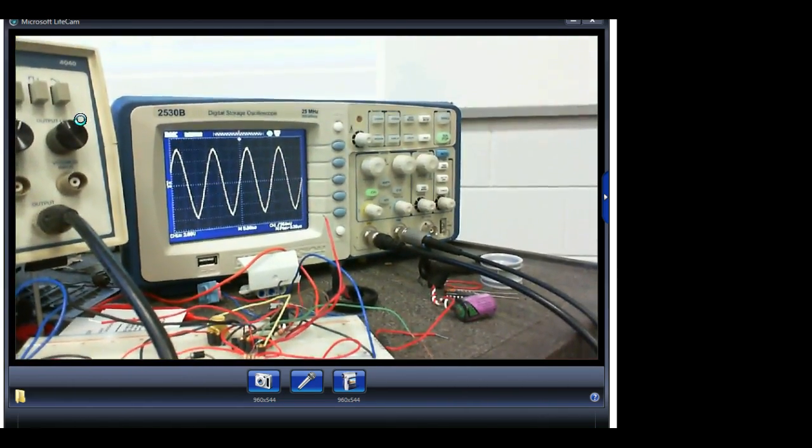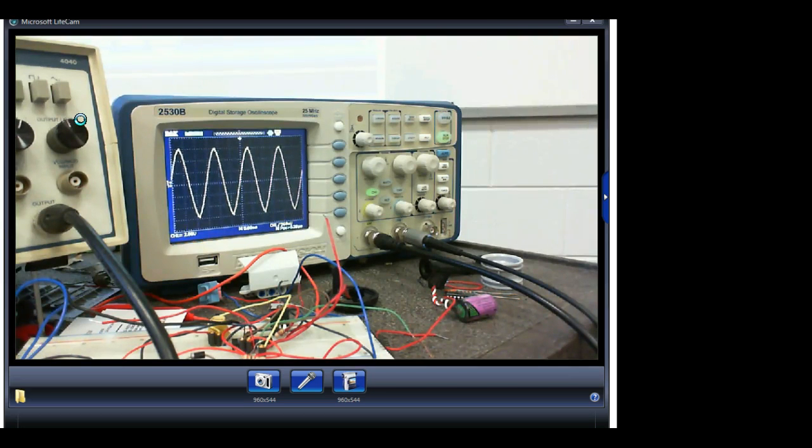So what should be the output voltage I'm going to measure on this thing? First of all, your scope measures peak to peak. What's the first thing you're going to do? You're going to divide that by 2, right? That gives me peak. So 12 volts peak to peak would be what? 6 volts peak. Everybody okay? Then what are we going to do? Then we're going to subtract 7/10 of a volt from that, right? You understand. That gives us V peak out. And then we're going to do what? We're going to divide that by pi.